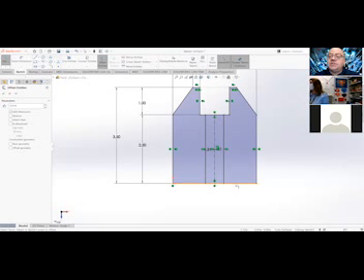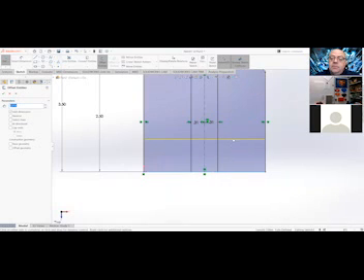Select your bottom line. So it's exactly like what we did in AutoCAD. We're doing the exact same thing. It's still a 2D drawing at this point, and we can do it the exact same. So then take the bottom line. I can go up or down, depending on which way you put the cursor. You also have reverse, so you can reverse it over here. It's a toggle. We want to go up.